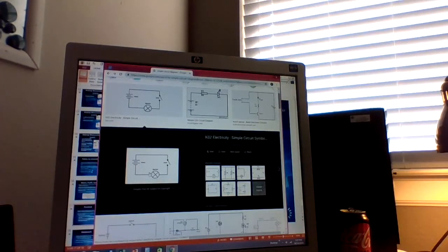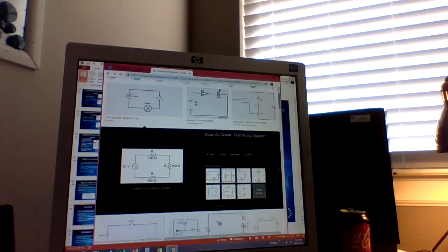And this one's going to have a certain resistance, okay? So I've got a V, I've got an R, and since I know the V and the R, I can determine the I. Sometimes the circuits will look something like this, okay? I've got a V, and then I've got 3 resistors in series. Now, you'll notice that it's got the squiggly line here. That means that's 10 volts AC.